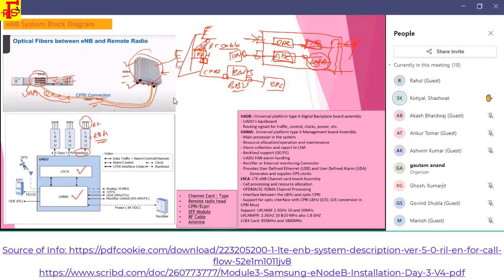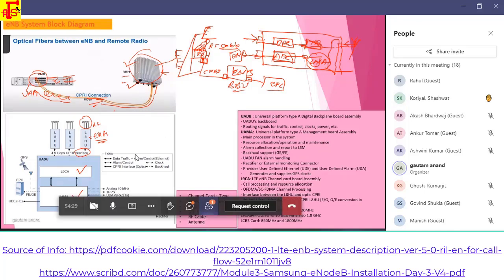I will explain that part. There is digital up conversion and digital down conversion. While it is receiving the digital baseband signal, through digital up conversion and digital down conversion it is changing it into intermediate digital samples, scaling the sample rate of the signal into discrete format.